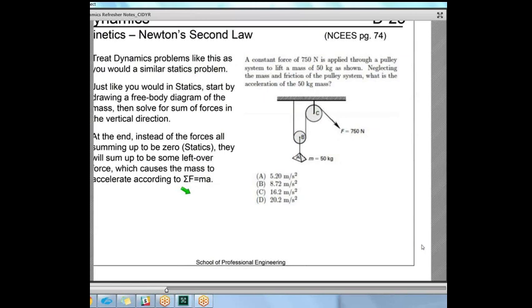So when we set up our statics problems for pulleys, we pretty much ended up looking at one of our 3 equations of motion, and we can do the same here. We'll look at our sum of forces in the y direction equation. In statics, that had to be set to 0, but here, in dynamics, it's just set to ma. Then we'll total up all of the forces. We've got this stuff moving up and down. There's a minus mg pulling us down, and there's a plus 2F pulling us upward. So see if you can solve that for a if you haven't already.